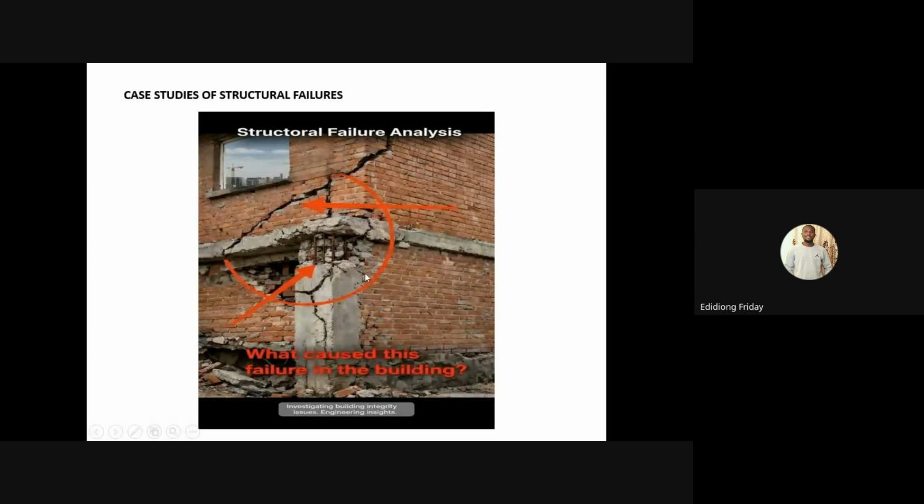But of course, we'll also run other tests. You can see serious cracks coming up on the column. This could be as a result of a poor mix, or the reinforcement actually about to buckle due to compression. So for me, we demolish the column entirely and then reconstruct it, taking it up to the next floor, and then reconstruct the brick wall or the block work.